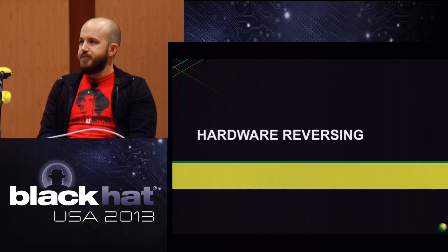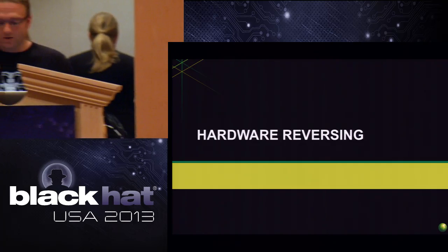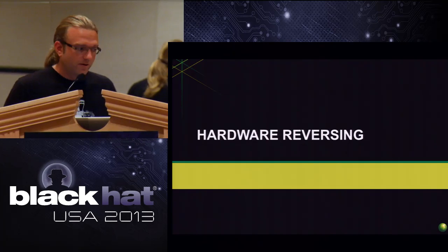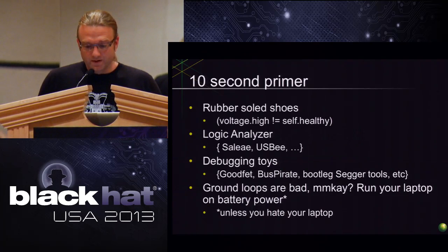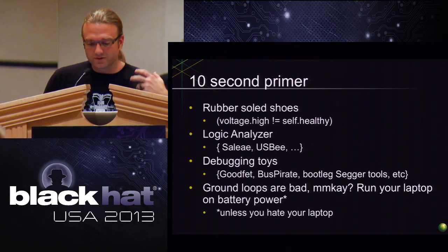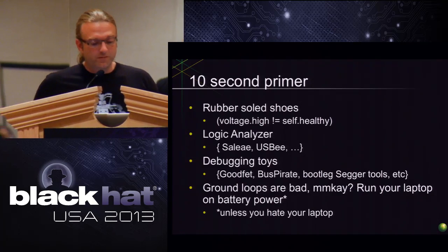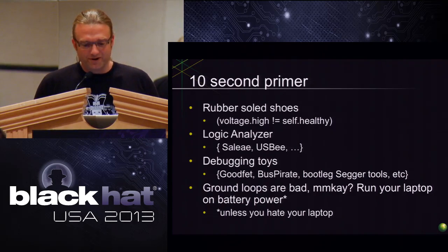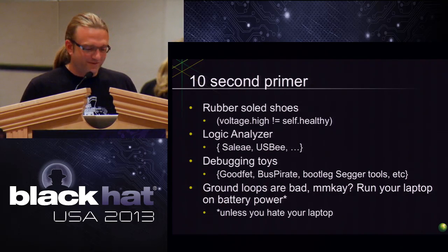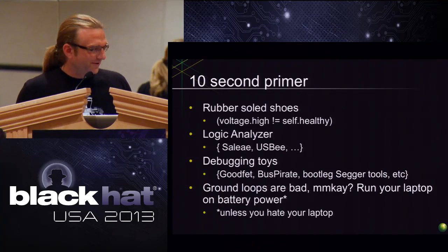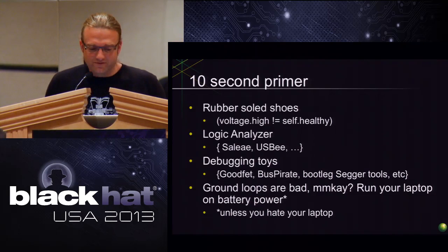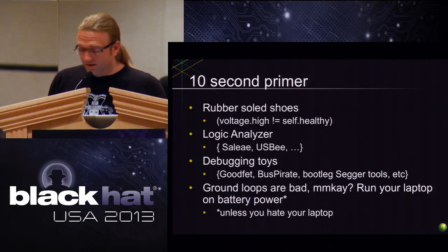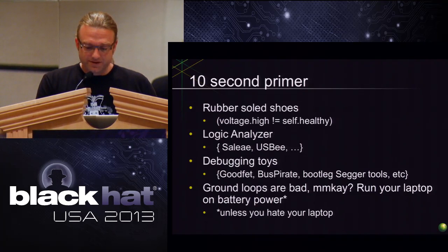Yeah. So our typical hardware reversing, just what we do, how we do it, how I attack a problem, how Nathan attacks a problem. We tend to work with smart meters. We tend to work with things like that. We're talking about a lot of voltage running through your desk at home. First warning that we hear at every presentation that is talking about smart meters is you have high voltage you don't want to touch. Touching high voltage sucks. We've all done it. Every one of us has at least run 110 through us, right? And it hurts. Don't do that. So be careful. Logic analyzers, they're great. You can start latching onto chips, which we'll see in a second. Start figuring out what's going on.